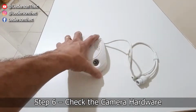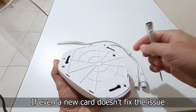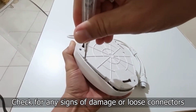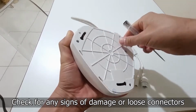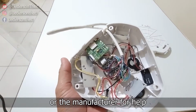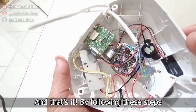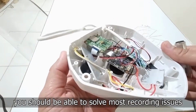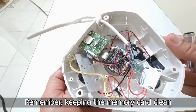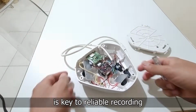Step 6. Check the camera hardware. If even a new card doesn't fix the issue, there might be a hardware problem with the camera itself. Check for any signs of damage or loose connectors. If necessary, contact technical support or the manufacturer for help. And that's it. By following these steps, you should be able to solve most recording issues on IP cameras. Remember, keeping the memory card clean, properly formatted, and using the right settings is key to reliable recording.